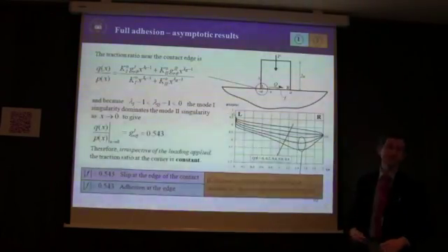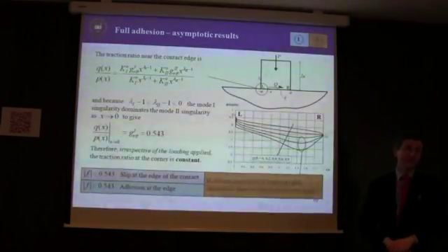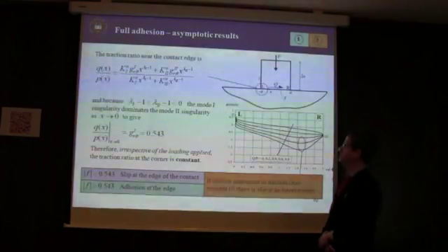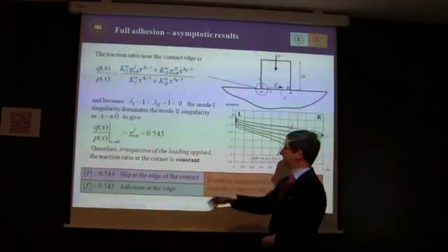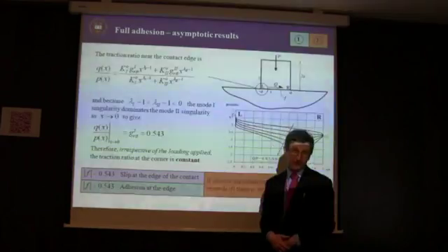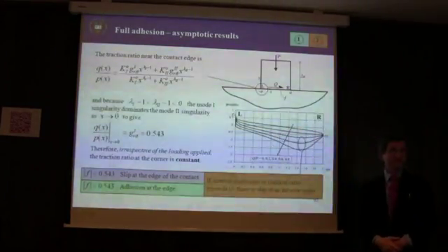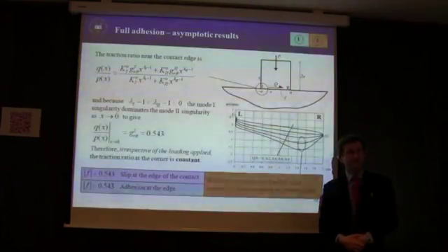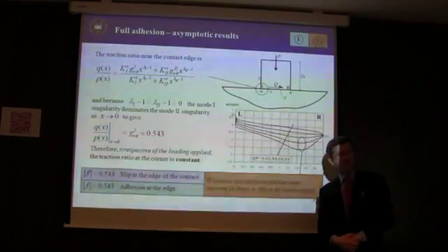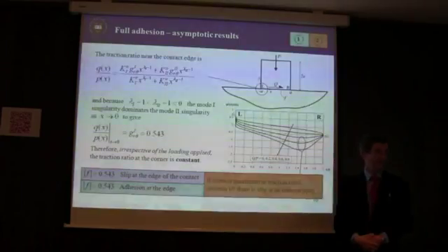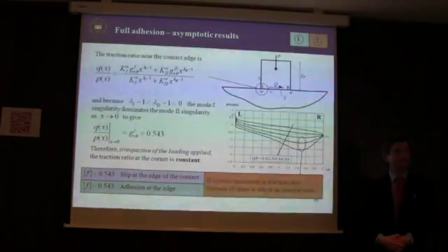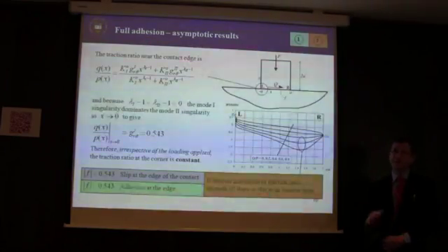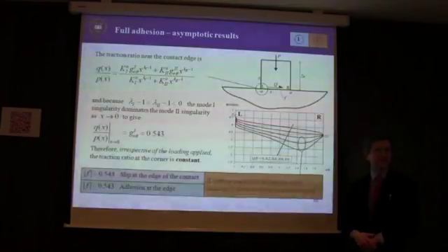Now what I want to do is to try and take this calculation a little bit further and to say that even if this condition is not satisfied, say the coefficient of friction here was 0.5, how big would the slip zones be? How big would the plastic zones be? Would the plastic zone envelop the slip, or would the slip envelop the plastic zone? All based, I hasten to say, of course, on an elasticity solution. So we're just looking at violations. There's no flow rule or anything like that in any case.